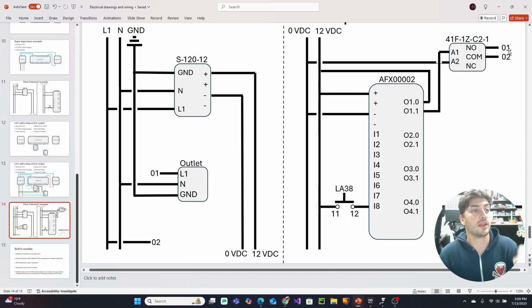But O1 and O2, which are linked to these, are physically represented by a number that says, hey, there's this disconnect between over here and over here. And sometimes you would want to link it with some additional letters as well. But this is just a way of calling out that the other side of this wire shows up somewhere else in your drawing package, and it's a way for you to correlate and track down those wires.